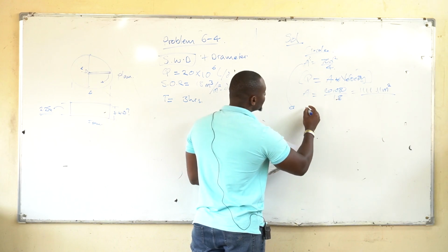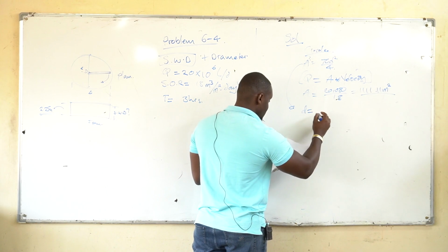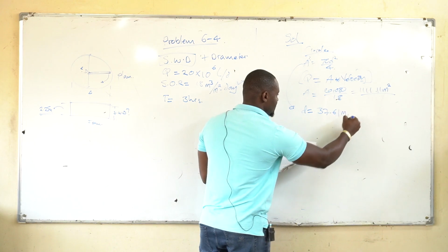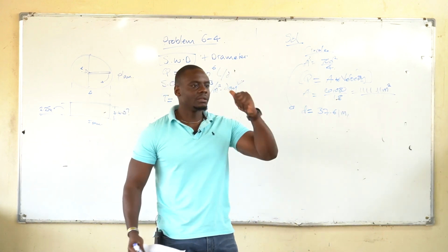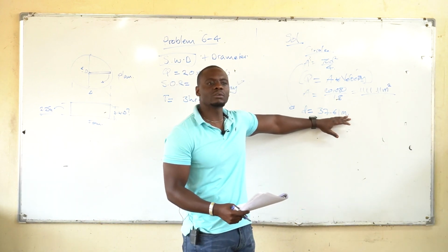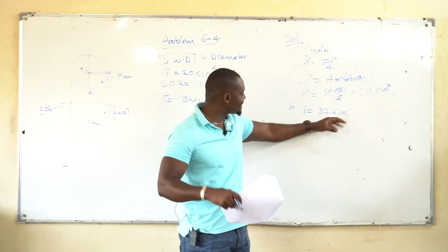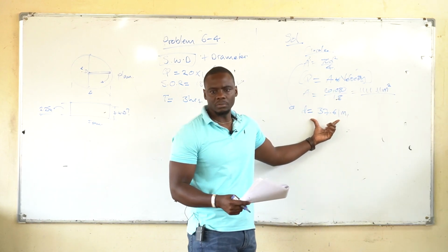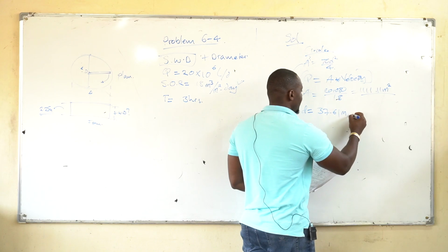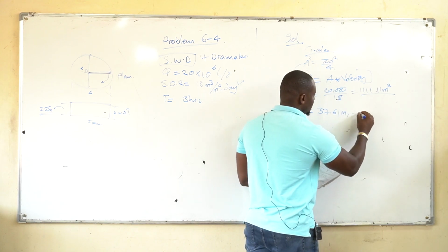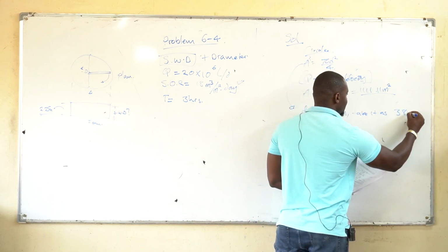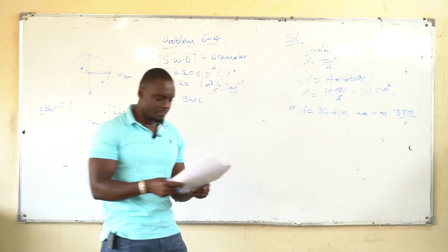I won't really take time here because you are good with this. So your value will be 37.61 meters. You are the consulting engineer. You cannot present this to the contractor. So you make a decision. Round this off to a value that is workable. You can think about it, right? It's up to you. Take it as a whole figure. So just say 38 meters of diameter.